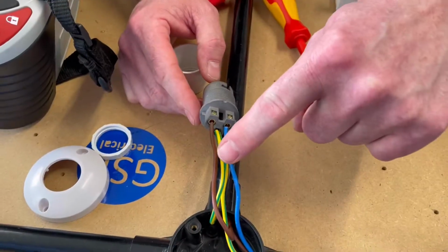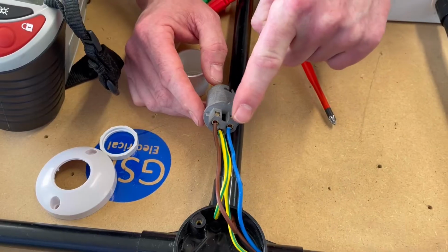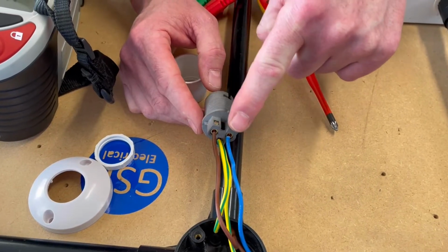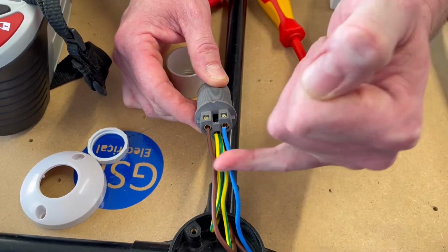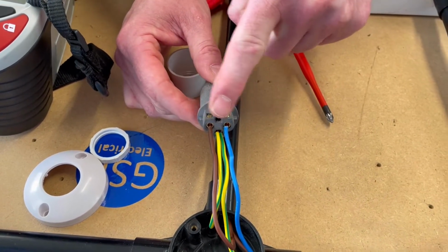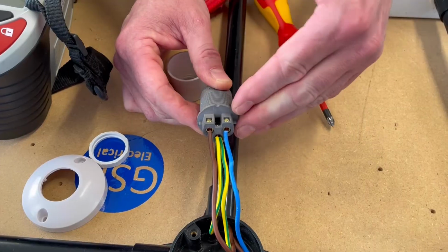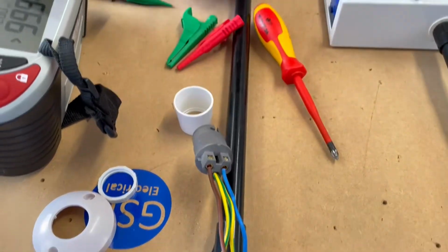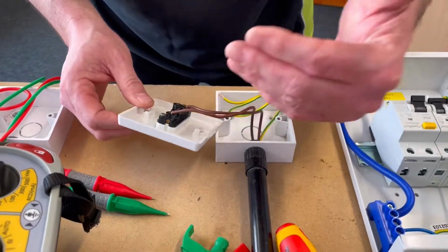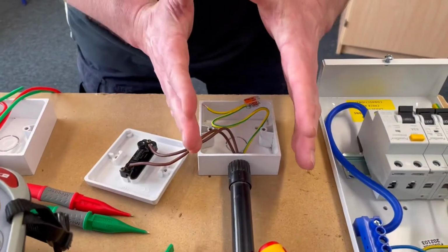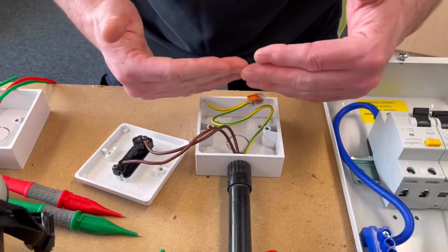So we proved the CPC got to here, and we proved the polarity of these connections here by visually looking at them. We confirmed the back section was for the earth symbol for the CPCs, and we knew that it didn't matter which one was line and which one was neutral, so we've done that as part of our polarity check. We also operated the switch when we were there, and we've left it in the on position, also part of the polarity check.